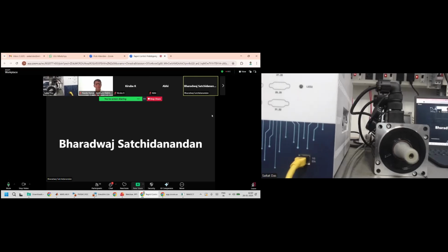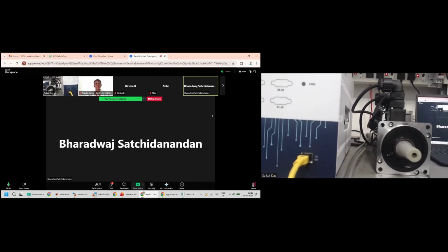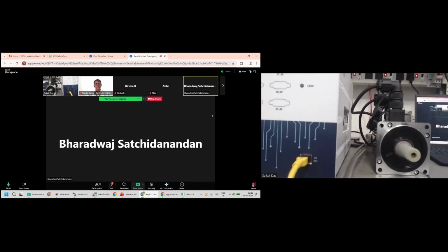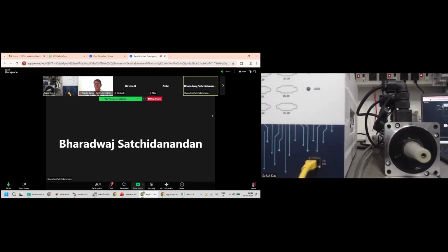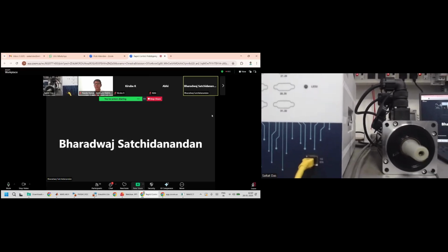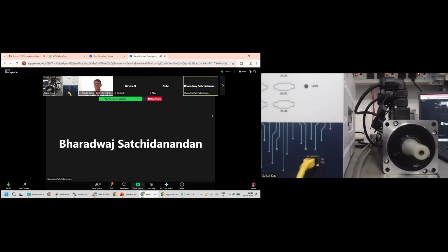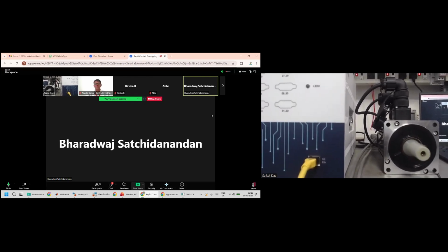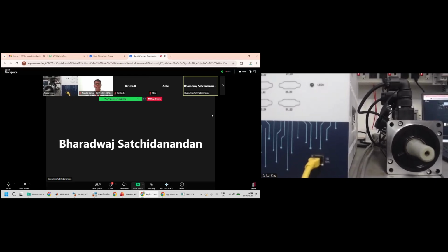Generally, yes, because the RCP systems will always come with all sensors embedded. When it comes to hardware testing, you need not worry about the hardware integration issue, the IO integration issue, or the PWM integration issue. You want a small RCP product that will help you interface with your hardware directly and run your control logics in your RCP box and validate your control logics.